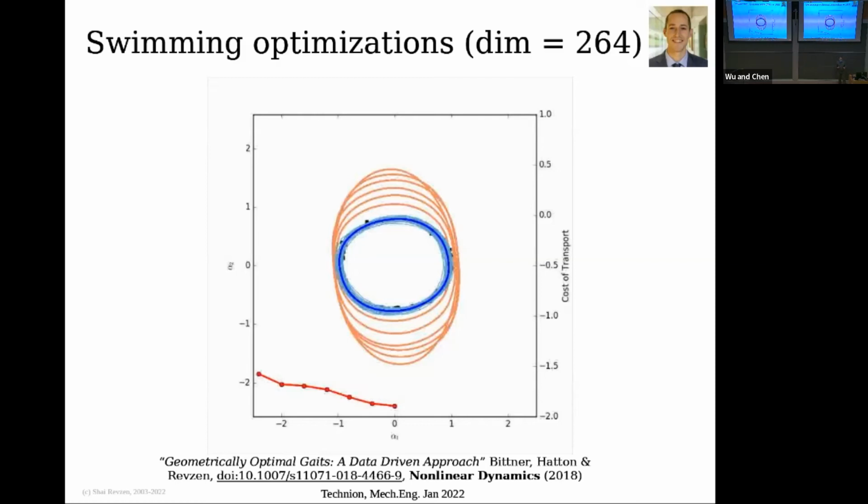I would say yes and no. And here's where something special happens for legged systems. Legged systems don't care about the symmetry of the environment except for their contacts, right? What the environment does where I have no feet doesn't matter. And so it's actually pretty easy to learn. You have another variable, which is where is your foot and what is the contact normal? And that's about it. So I think it's still easy to learn. I think this is where legged systems have a leg up, if you will. So they don't need the full symmetry of the environment.